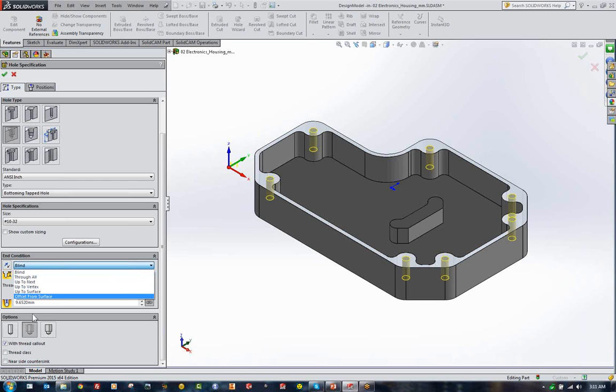It looks at which of this list was chosen. I doubt very seriously that we can get SolidWorks to create a variable in here for us. So what we decided to do instead was simply teach it to look for whether the value is in hole diameter or in through hole diameter. It tells you immediately whether it's a blind condition or a through condition. It's not a logical check, but it works.